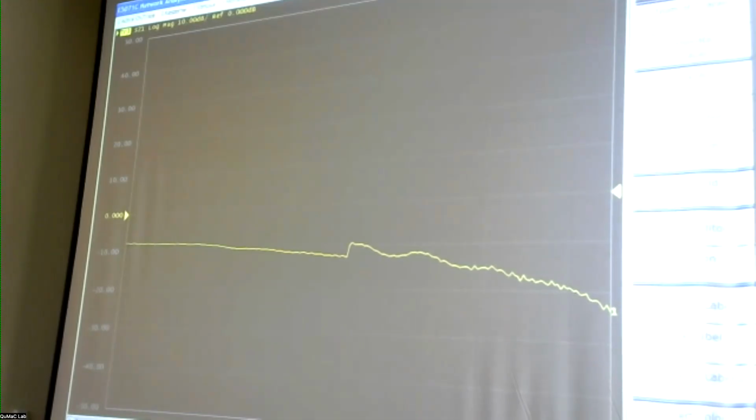Why is that? Because otherwise the amplitude is going to come out here. It's going to see an open end. It's going to reflect that and combine with that one and this one in some strange way. So this is how you should test it if you're only connecting it to 2 ports. If I have connected this to one of the other ports, then it's fine because that is a 50 ohm convention.